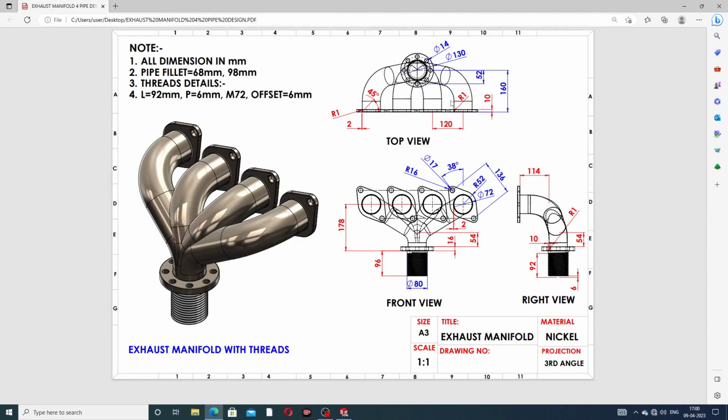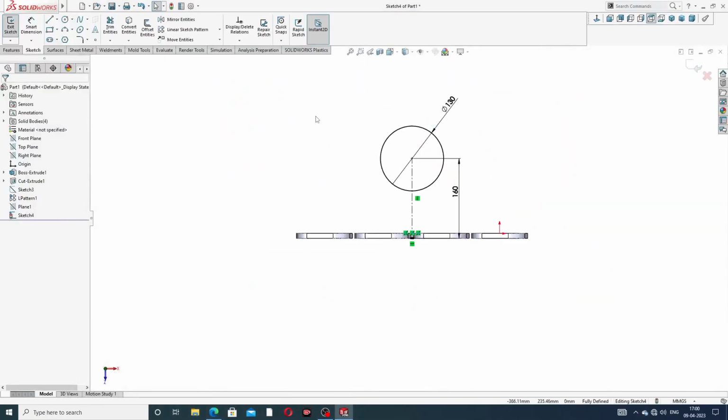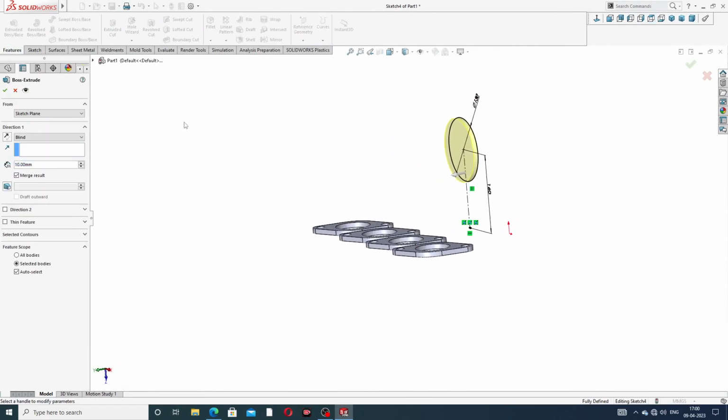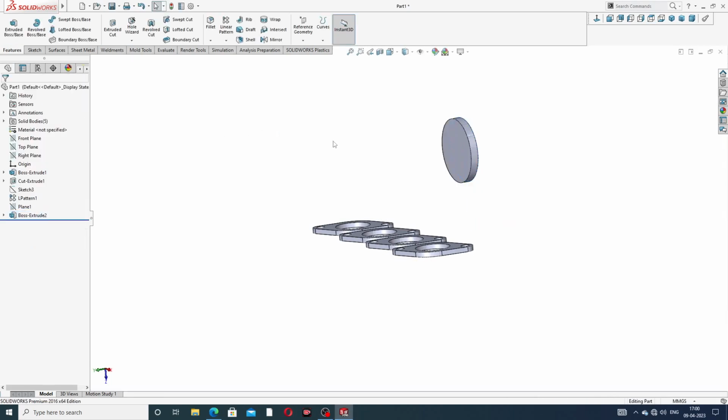And this thickness is, okay, this thickness is 17 millimeter, perfect. Okay, 17 millimeter. Okay, and both are black color, meaning this is fully defined, and use an extrude boss, and this thickness is blind, and use 16 millimeter is perfect, and click OK.